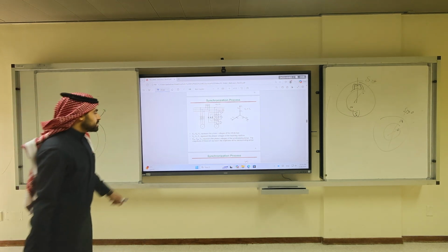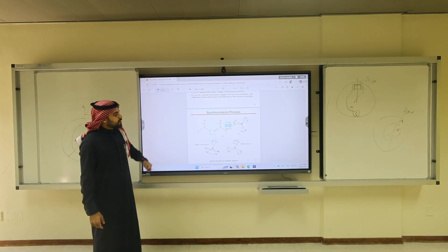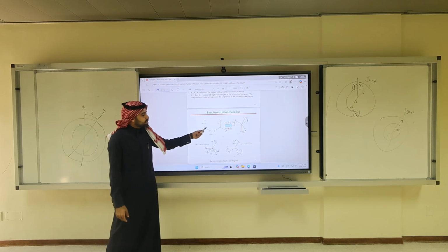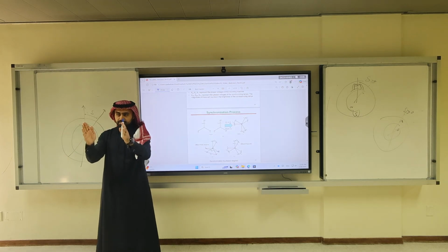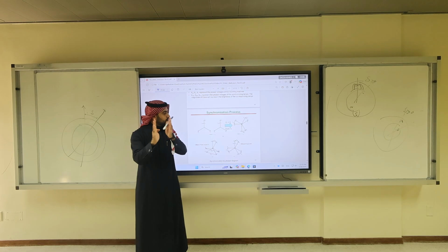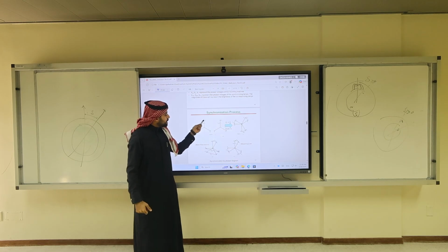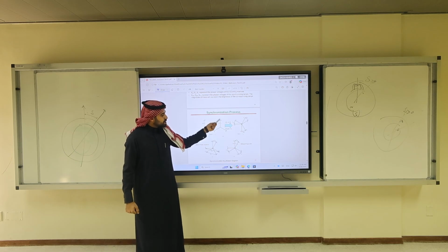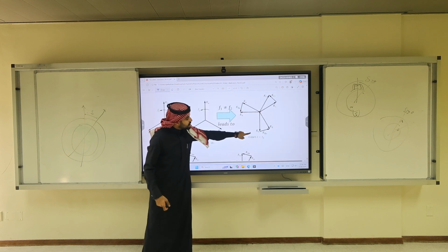Okay, synchronization process. That's what you need to know. Now let's see, for example, what will happen if you change the frequency. If you start from the same, all the phasors are in line. After some time, you will notice that the phasors would be deviating away. So for example, EA, which is the infinite bus, and E small a, the incoming machine, will have a voltage drop. You see these arrows?